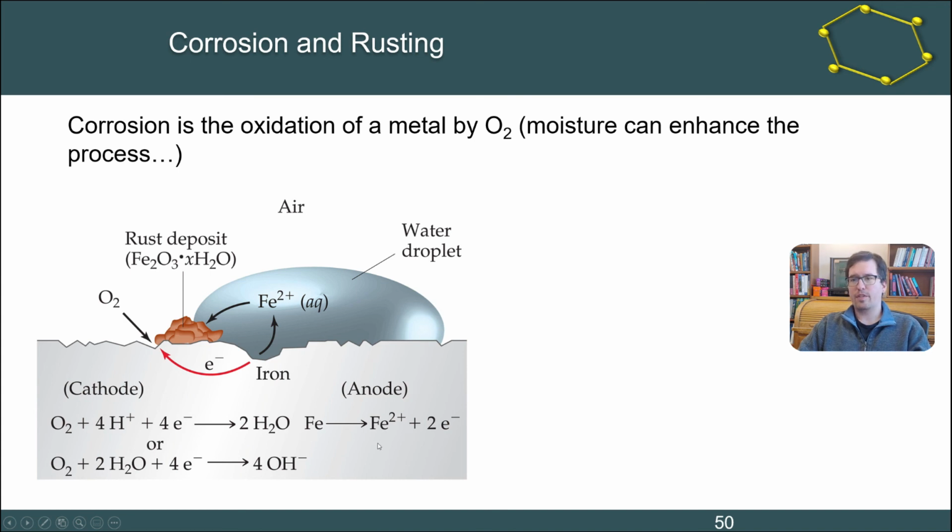This is a little bit of a complicated process. It can be oxidized directly to iron 3. Typically, the actual rusts themselves have iron in a plus 3 state. So as we see here, Fe2O3, iron must be plus 3. And so that oxidation can happen all in one step from Fe to Fe3+, or it can be oxidized to Fe2+ in the water layer or in, say, even a water vapor layer, then rapidly hydrolyzed then to Fe3+.